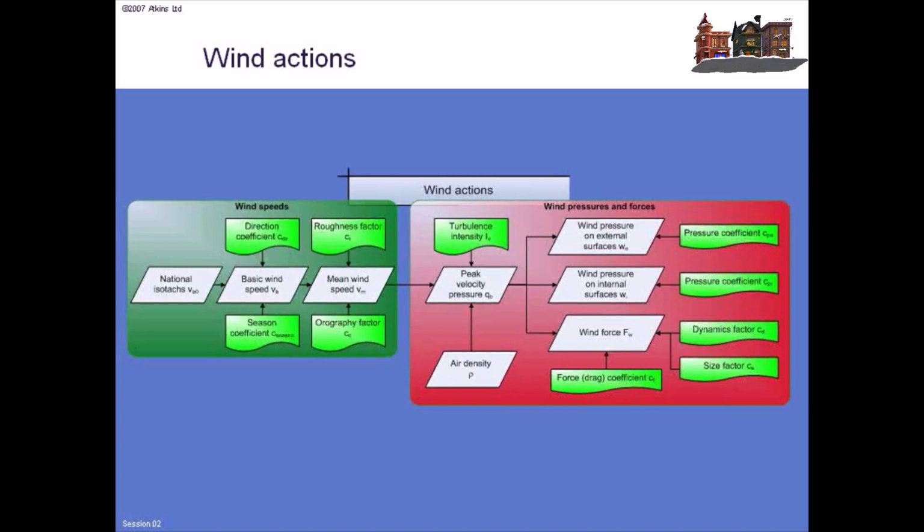And this is if you're going down to low frequencies, sort of typically below 1 hertz, then you start running the risk that the gust pressures in here are not adequate for your design, because it may be that the natural frequencies in the gusts can actually be in phase with the structure, and that's not allowed in BD 37. BD 49, which covered aerodynamics, said if your natural frequency was less than 1 hertz, then you need to check turbulence response, and you need to go off and do a dynamic analysis. This is slightly more helpful, and it basically gives you some formulae to use in that situation for low frequencies where turbulence response is a problem.